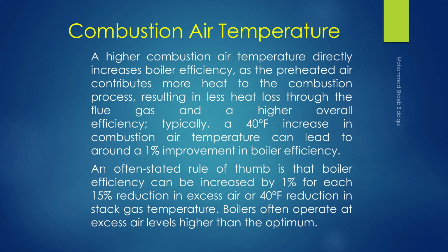An often stated rule of thumb is that boiler efficiency can be increased by 1% for each 15% reduction in excess air or 40 degrees Fahrenheit reduction in stack gas temperature. Boilers often operate at excess air levels higher than the optimum.